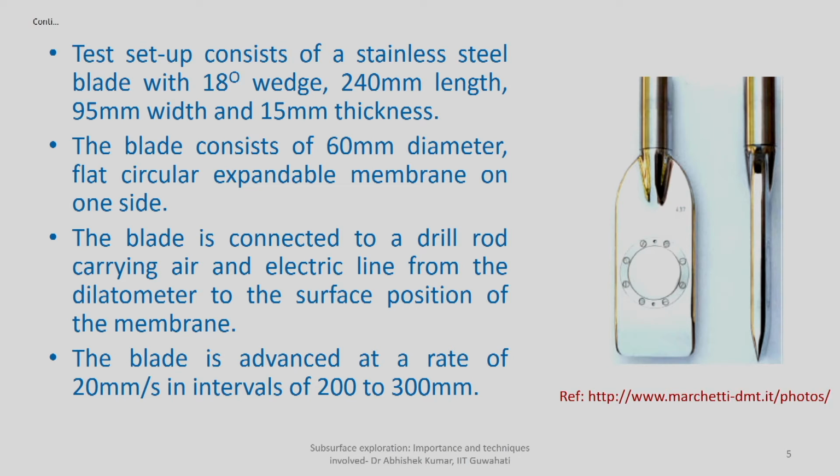The test setup consists of a stainless steel blade. You can see here a stainless steel blade with an 18-degree wedge angle, 250 mm length, 95 mm width, and 15 mm thickness. So this is the dimension of the blade itself. 250 mm is almost 25 centimeters; 95 mm is the width at the base and 15 mm is the overall thickness.